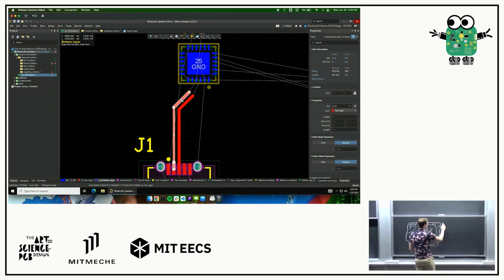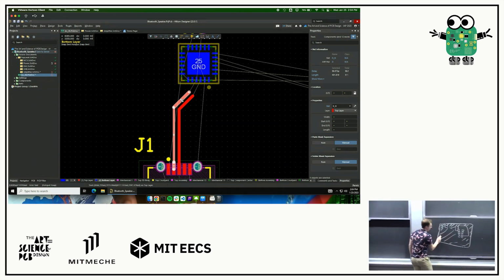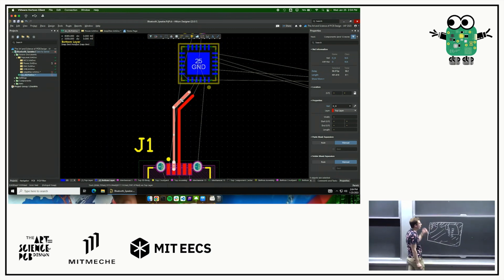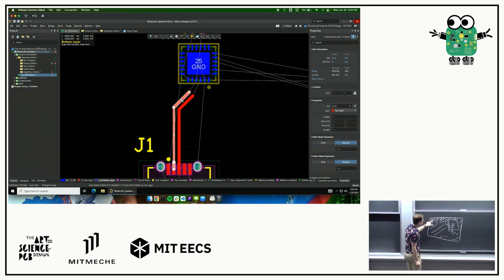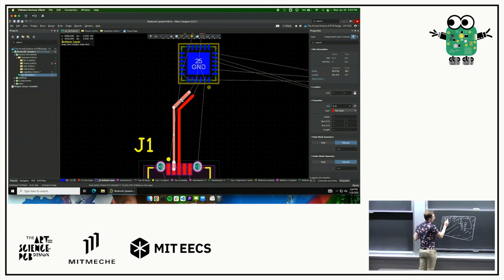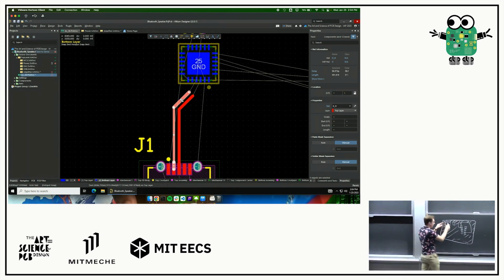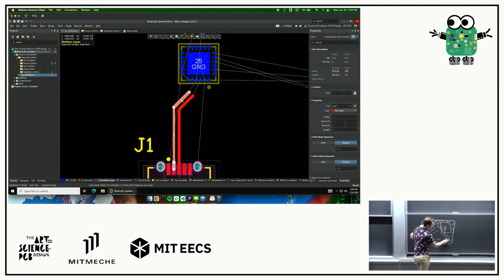Oh, like instead of just a big wire that goes around here and just connects everything? Oh, that's an excellent question. Let's say I have this part over here, and let's say this is connected to ground, and there's some other part over here that's also connected to ground. If I have a long, thin piece of copper over here, what circuit element does that look like? It's like a little resistor, right?